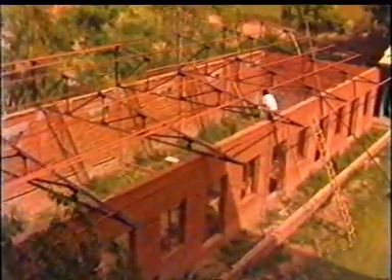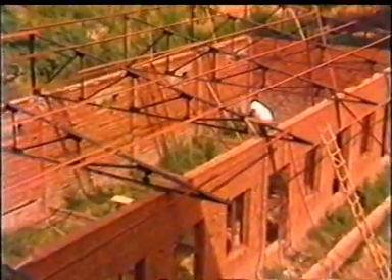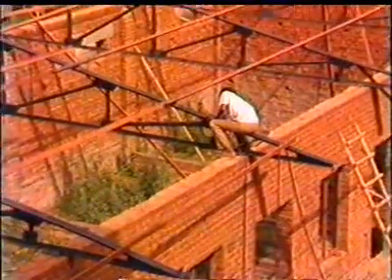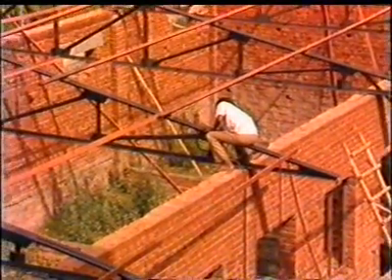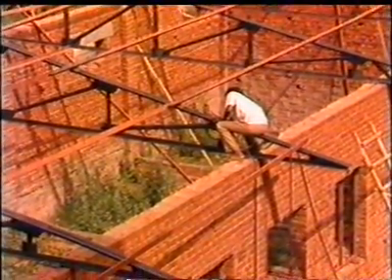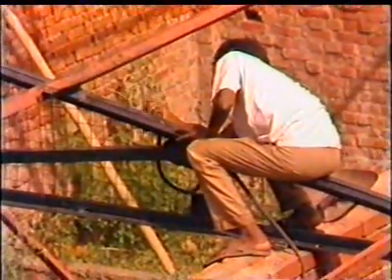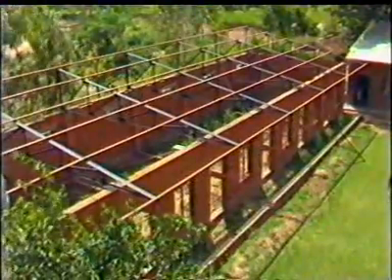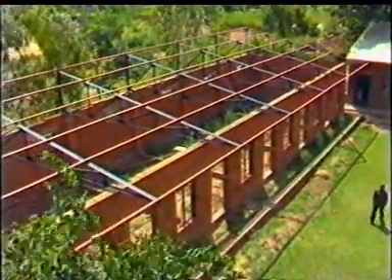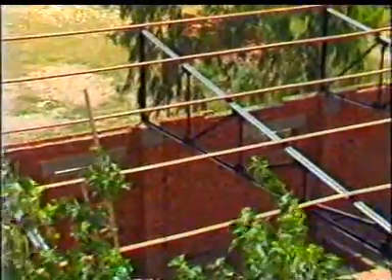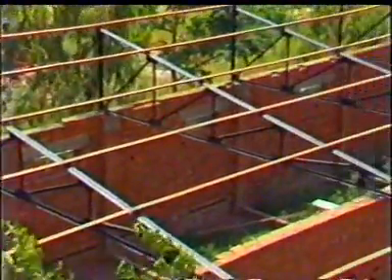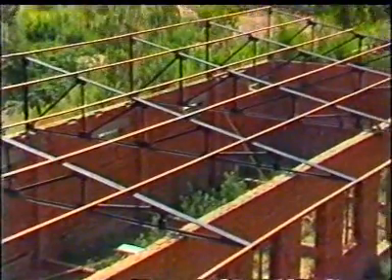Trusses support the purlins at suitable intervals on the principal rafter and are connected by cleats. The purlins support AC sheets and transfer loads to the truss joints. Spacing of purlins is so adjusted that the cutting of sheets is avoided, and normally it rests over or very near to the joint.